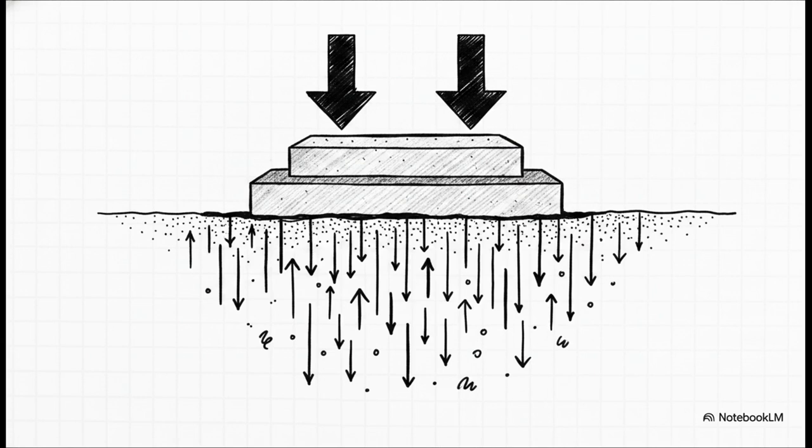Well, because in practice, real foundations, like standard footings or those massive concrete mats, are neither perfectly flexible nor perfectly rigid. They exist somewhere in the messy in-between. Engineers use these idealized models because they explain exactly why contact pressure is almost never truly uniform, even when a building looks perfectly symmetrical to us. Assuming uniform pressure is often used in simplified design, sure, but it is ultimately just an approximation. Different stress, strain, and confinement characteristics completely change the hidden physics happening beneath the floorboards.